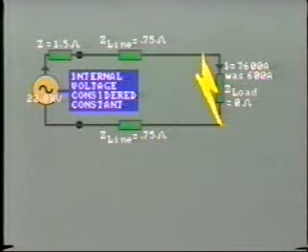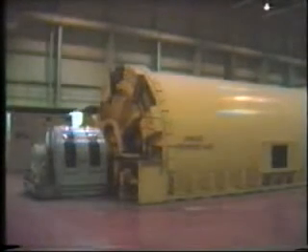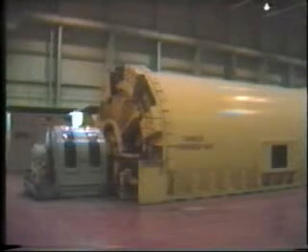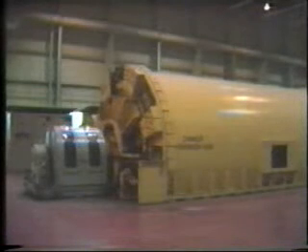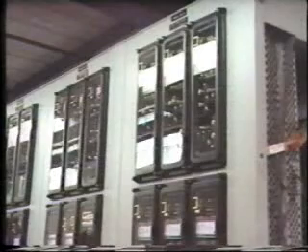When studying fault conditions, we always consider that the internal voltage of the generator remains constant. This is based on the assumption that the time interval will be extremely short before protection equipment clears the fault. In practice, it is probable that the generator automatic controls may attempt to increase generator internal voltage in order to compensate for some of the voltage drop downstream. However, this would take some seconds and therefore should not interfere with the operation of protection relays, nor with our studies of fault characteristics.